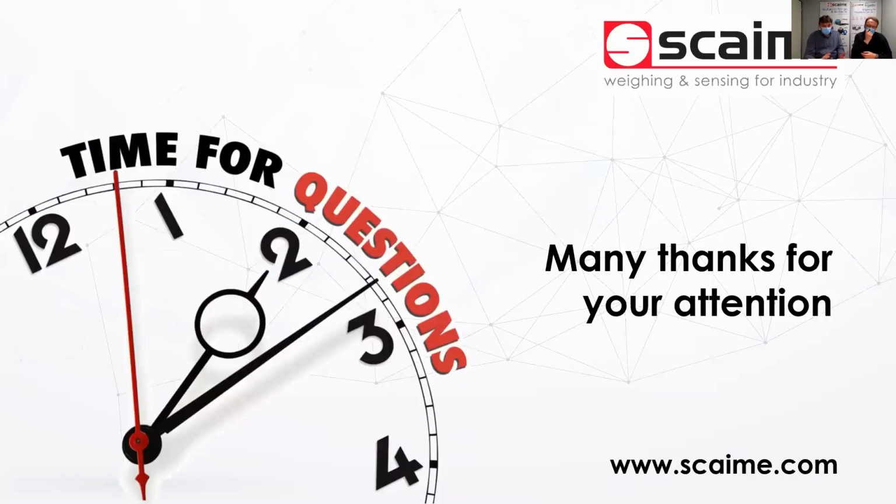I assume that we saw on one of the slides that the capacity of the memory is 32 gigabytes. Yes, gigabytes. Of course, it takes a long time until you fill this memory. But what happens if you have reached the maximum capacity? It will stop recording. So you have to clean and reset. It can be quick if you have 2 kilohertz with 100 sensors. Yes, we don't recommend using internal memory.